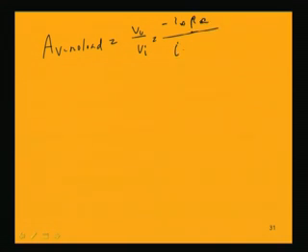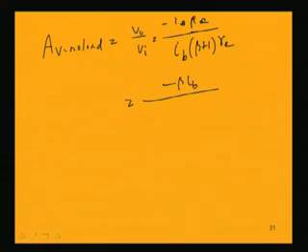Vi is IB into beta plus 1 RE. So here I naught can be written as beta IB into RC by IB beta plus 1 RE. Then IB cancels. So this is the value of the no load voltage gain, whereas the loaded voltage gain is with respect to taking into consideration load resistance, which we have already done. So we can find out the difference.